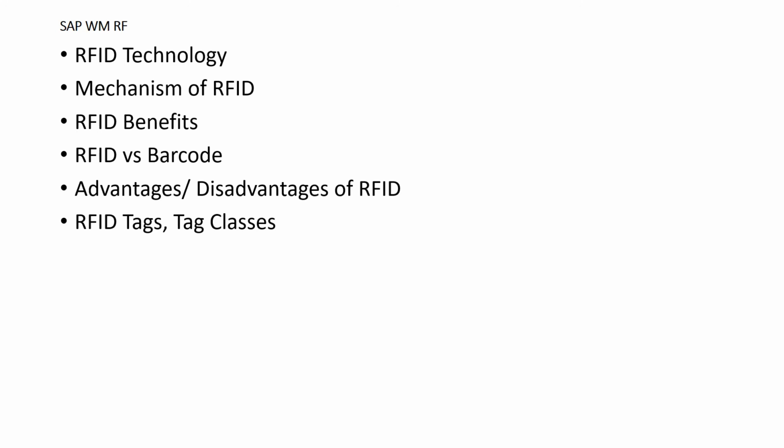The antenna is made from one of many different conductive materials, including silver ink, aluminium, and copper. Next, the tag chip itself is connected to the antenna using techniques such as wire bonding or flip chip. Finally, a protective overlay made from materials such as PVC laminations, epoxy resins, or adhesive paper may be added to allow the tag to withstand physical conditions found in many applications such as abrasion, impacts, and corrosion.